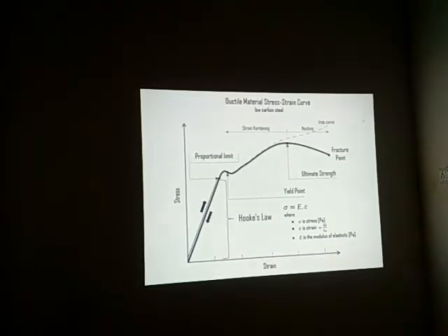It means that the stress is directly proportional to strain, and the slope of this straight portion of the plot is constant. So this slope is basically governed by Hooke's law, that is within the elastic limit, the stress is directly proportional to strain. It means that within this plot, if we release the load causing the strain, then the deformation is recovered back. The material comes back to its initial state, and this way it performs as a purely elastic material.